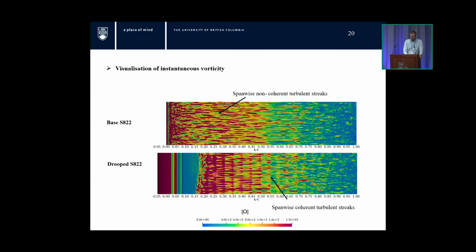Then we see much more significant span-wise coherence over a long period, from about 25 to 40 or 45% chord, and that span-wise coherence doesn't go away until maybe even around 80 or 90% chord. So the amplification of disturbance is much more gradual, and it maintains the memory of the 2D inviscid instability, or at least the 2D instability, for much longer, where we see this span-wise coherence in the turbulent streaks and their impression on the skin friction.